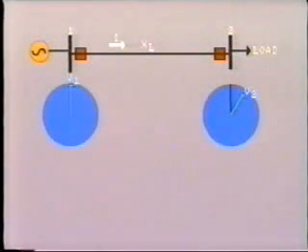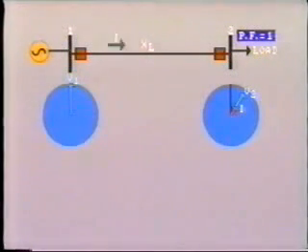If we consider the load demand at bus 2 to be at unity power factor, then the current is in phase with V2 as shown here. As this current flows through the transmission line, the inductive reactance produces a voltage drop, IXL, which is 90 degrees out of phase.